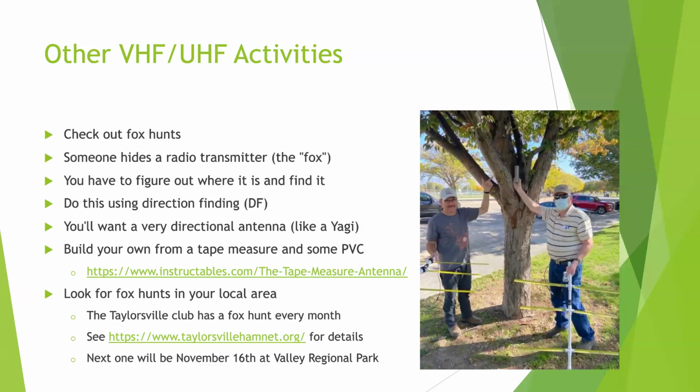Yeah. I should point out, it's not just people transmitting illegally intentionally either. There was a situation a couple of years ago where in August in the afternoons, all of a sudden there was something interfering with the 146.62 repeater. I remember that. It turned out to be an overheating doorbell transformer in an attic. And as the afternoon went by and it got hotter and then cooled off, the frequency would drift up and down the 2-meter band. And the only reason they noticed it on 6.2 is because it doesn't use PL tone.